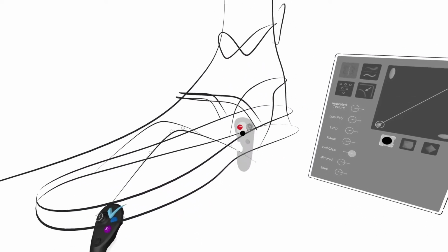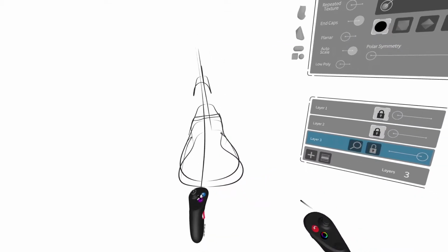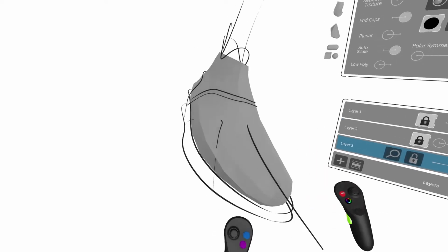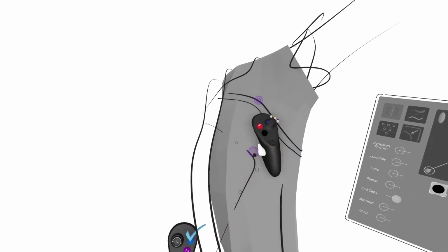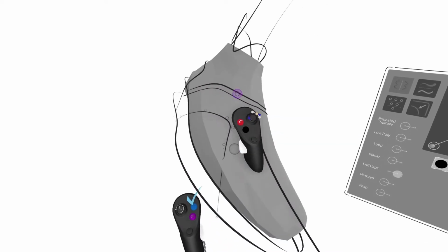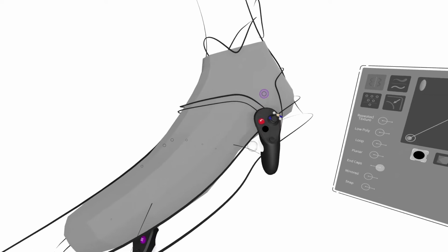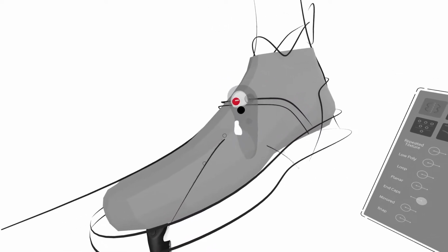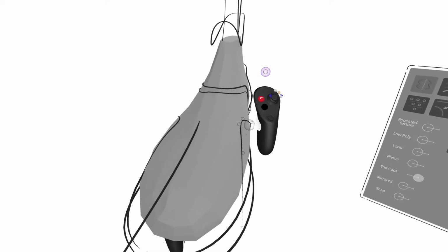And I might want to bring the shoe last in at this stage, because I'm just realizing that the contour of the foot is going to really make a difference here. Yeah, exactly. So we're going to want to add points as well, so we can see that we need to achieve a certain type of curvature there. We're going to have to bring a point in to do that. I'm predicting that's probably the same thing here. Yeah, so let's do that as well.